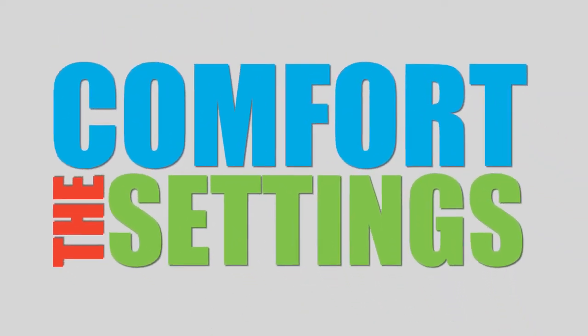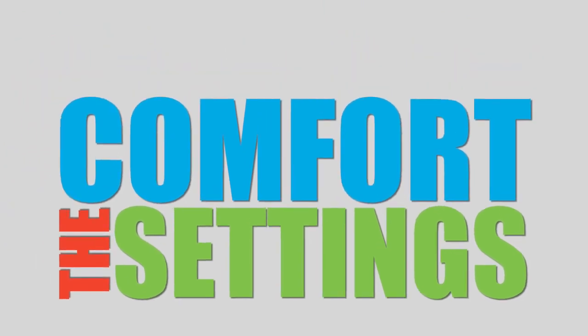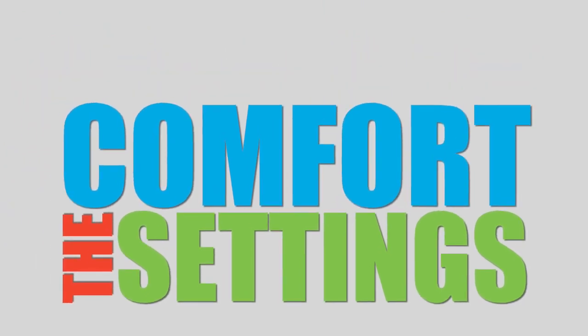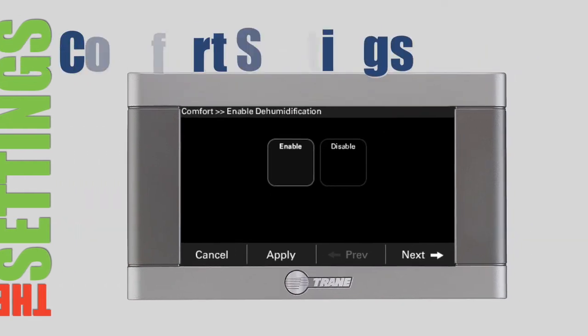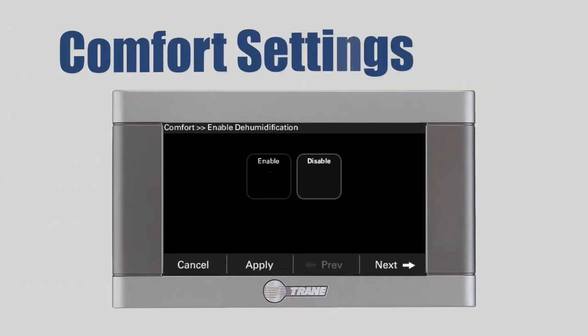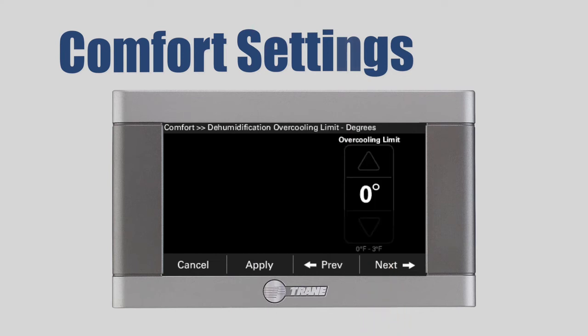Comfort Settings. Comfort Settings allows the customization of system performance management. Press Edit to modify the control's default comfort settings. Enable or disable dehumidification and press Next. Now set the dehumidification overcooling limit and press Next.